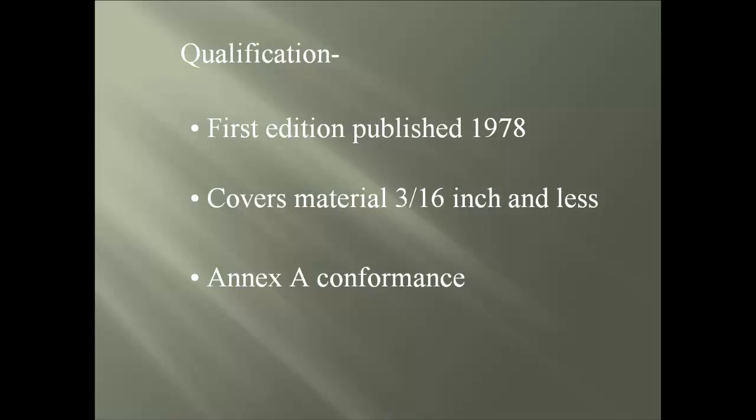This table covers electrodes, types of weld joints, the design of welded connection, pre-qualified WPSs, qualification tests for both the procedure and welder, preheat and interpass temperatures, fabrication procedures, visual inspection of weld profile, and lastly, stud welding, while also working with the requirements of D1.1.